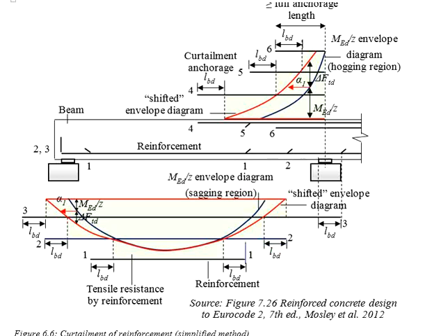Theoretically, stress develops along the increment of the anchorage length, until it achieves the full anchorage length, where the full stress is developed within the steel bar. However, the simplified model only considers the full stress developed within the steel bar upon achieving the full anchorage length. Prior to achievement of the full anchorage length, it is assumed no stress is developed in the steel bar.